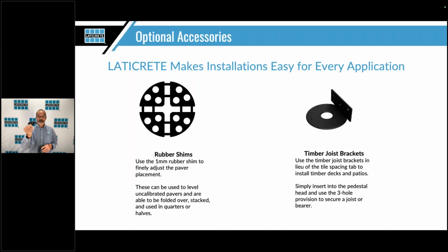Now I've seen guys use a single one, drop it right in there, and basically that will take out maybe that little imperfection in the bottom of the stone or the paver or the tile, whatever you've put on there. It'll take out a little bit of that imperfection. Let's say you're using stone and you got a really big imperfection. You can take these, fold it into 4. Like I said, once again, it goes right on top of it.